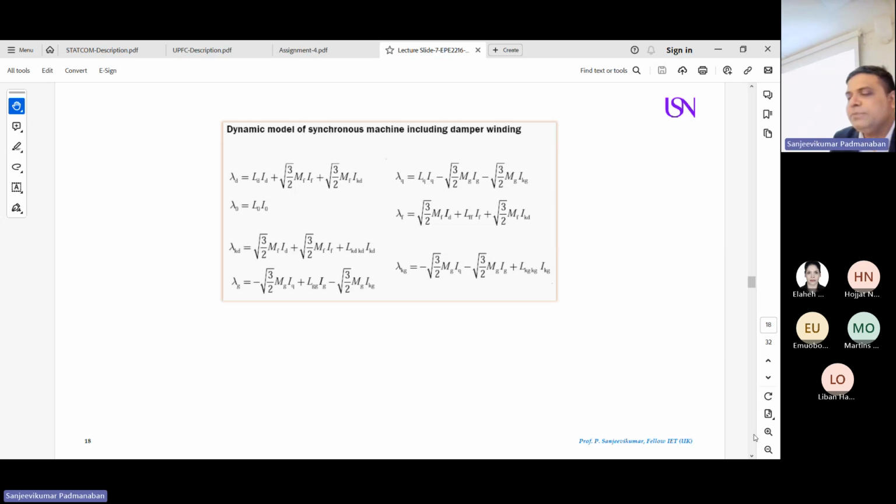Okay. So usually, if you look at the DC machine, we have an armature reaction. So what is armature reaction? Due to the continuous rotation of your rotating part, which is the armature, and you have fixed poles, the poles will not rotate. Only the armature will be rotating. So you get a neutral axis when the pole of your rotating armature and the fixed pole are exactly in the same sequence or vertical. For example, the easiest way to say it is that they exactly coincide vertically.